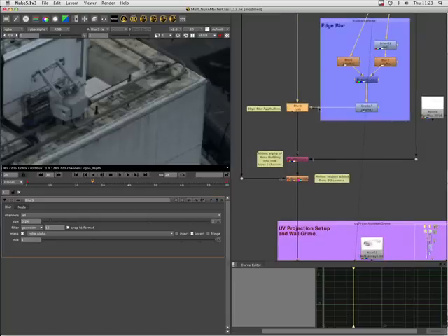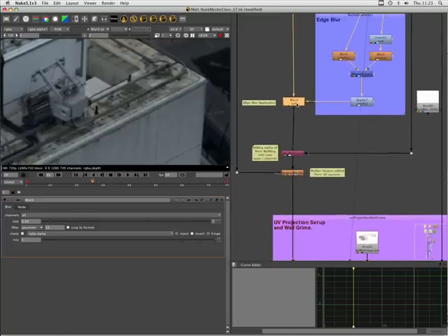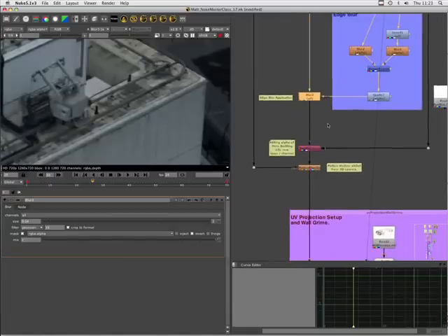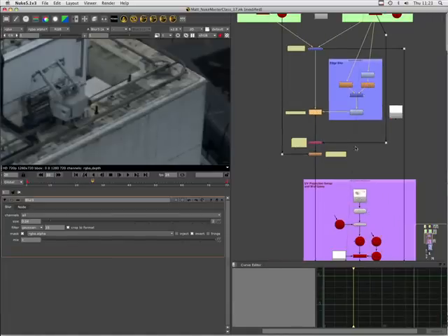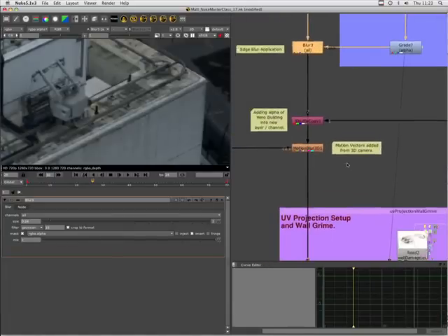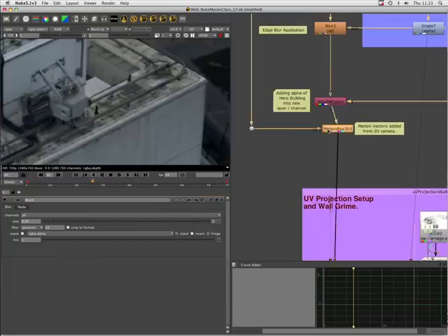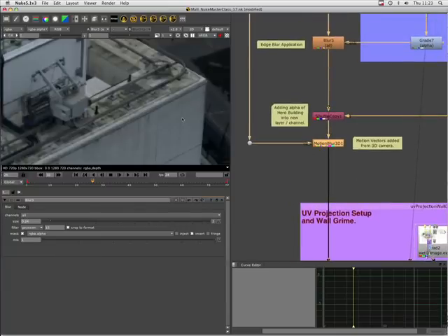And I believe if you're using Shake, it's the normal way of getting things in and out of nodes, but there are other ways you may know inside of Nuke to do this. Okay, so from here, I'm just adding the motion vector information from the scanline renderer. It's basically combining the foreground and the background motion vectors in here, and we will be utilizing that in a minute.